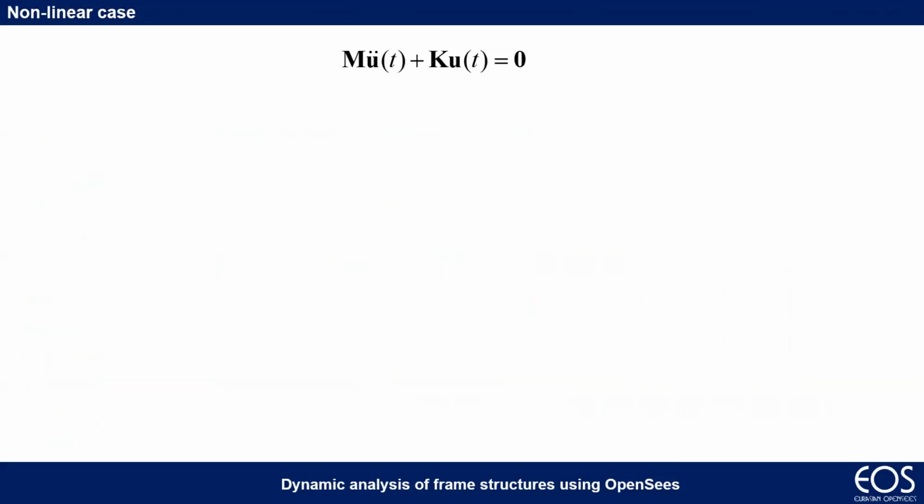The mass matrix. What about the stiffness matrix? OpenSees is highly devoted to nonlinear analysis. Which stiffness matrix do I have to use? Yesterday afternoon, you saw that in OpenSees I can declare nonlinear stiffness problems with different approaches. So which stiffness am I using in OpenSees when I compute the eigenvalue?